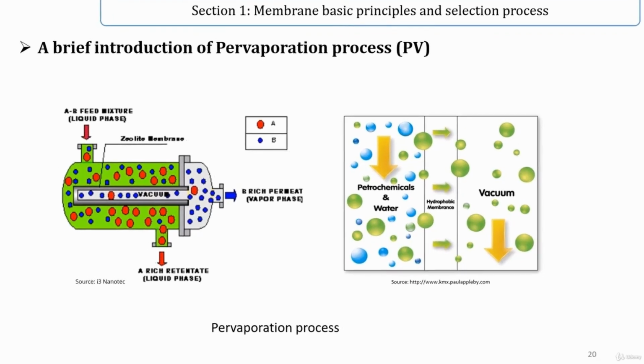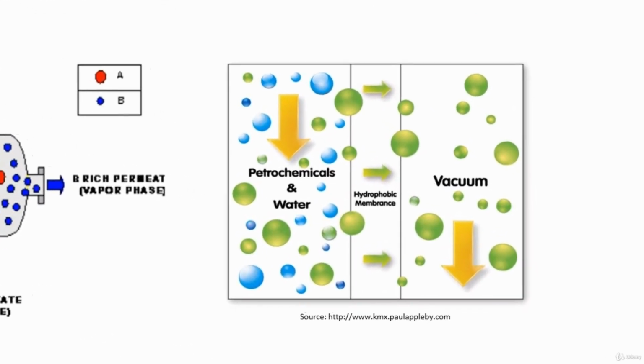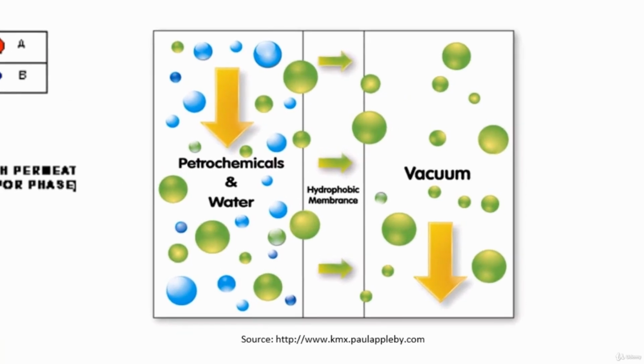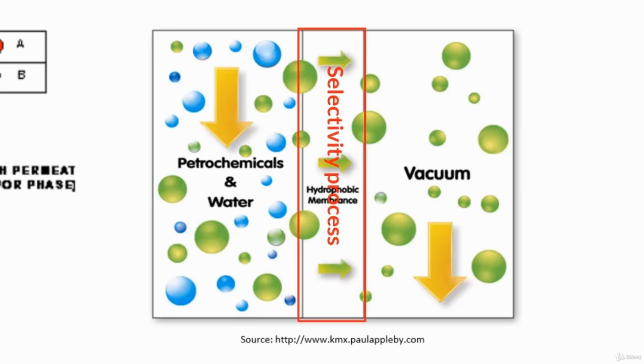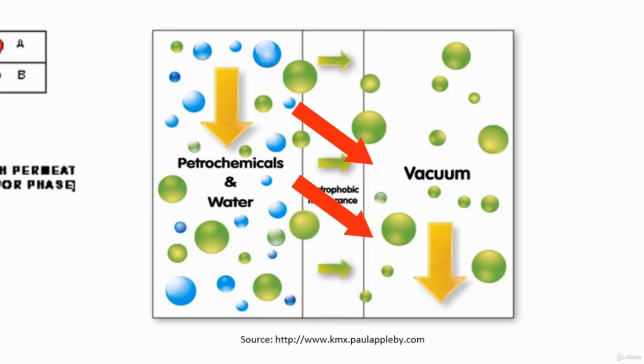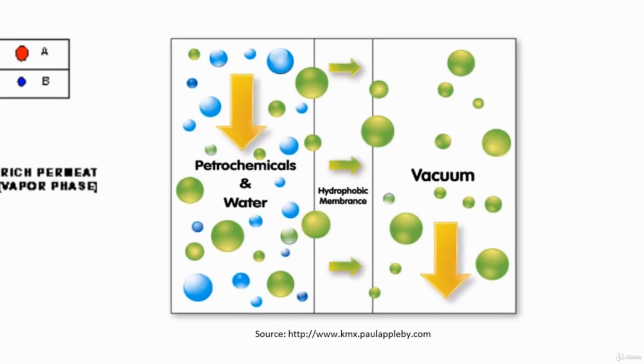If I want to explain the solution diffusion mechanism in a pervaporation membrane, at first, on the feed side of the membrane, diffusion takes place in the liquid boundary layer. Second, molecules of a component are selectively partitioned into the membrane. Then diffusion takes place through the membrane mixture, and in the end desorption into the vapor phase on the permeate side.